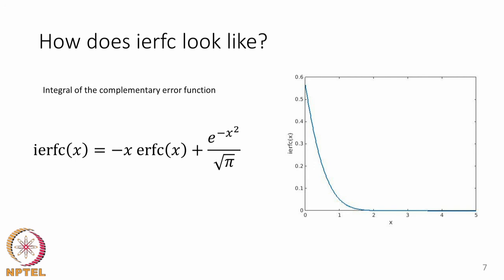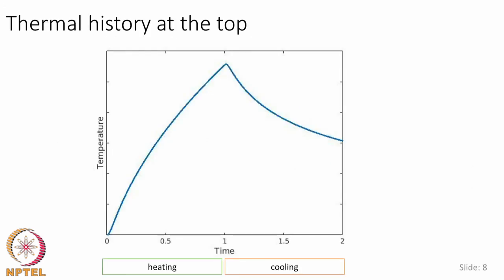Now, basically this solution is going as a smoothly varying function going downwards and reaching a flat value of 0 as you keep on increasing the distance. Now, this is very much suitable for the temperature distribution within a weldment, because we know that as time proceeds the temperature would come down to the preheat temperature or the ambient temperature after some time.